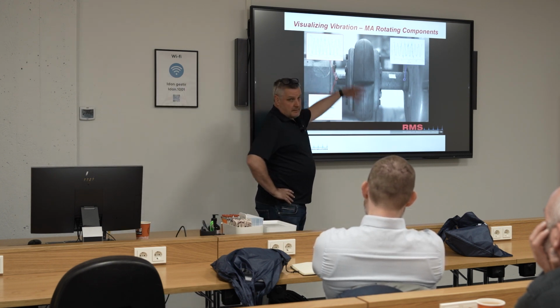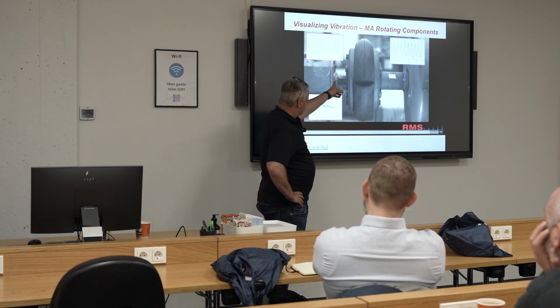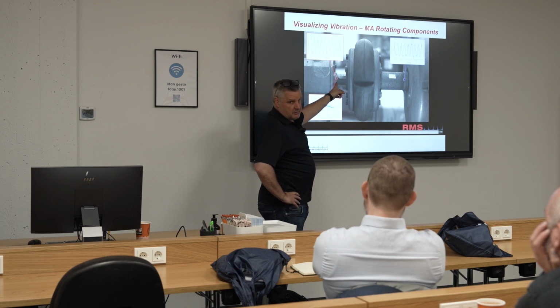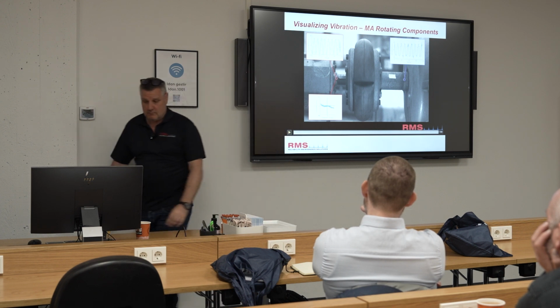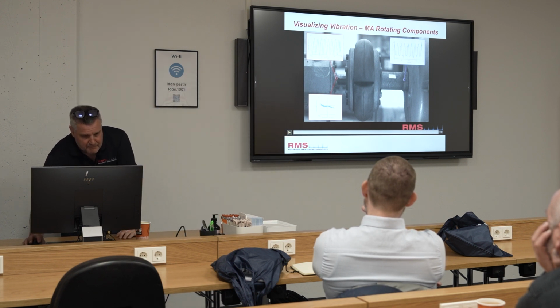So that's spinning, but what we're looking for is other things in the signature other than the rotational frequency from the tacho. It's very effective if you're looking at couplings, because that slows the coupling right down, and you can see the actual thrusting across there because we've synced it. Just another application, really.